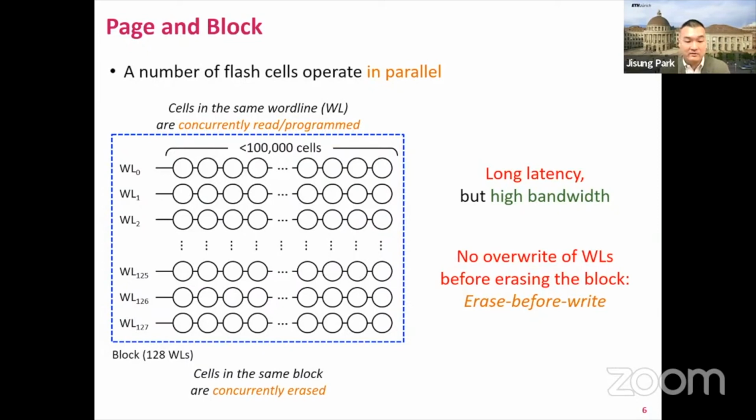For sure, we can issue a program command to program the word line, because NAND flash is just a passive memory device. But in most cases, doing so cannot store the correct data. This is because it is impossible to overwrite a 0 cell to be a 1 cell.